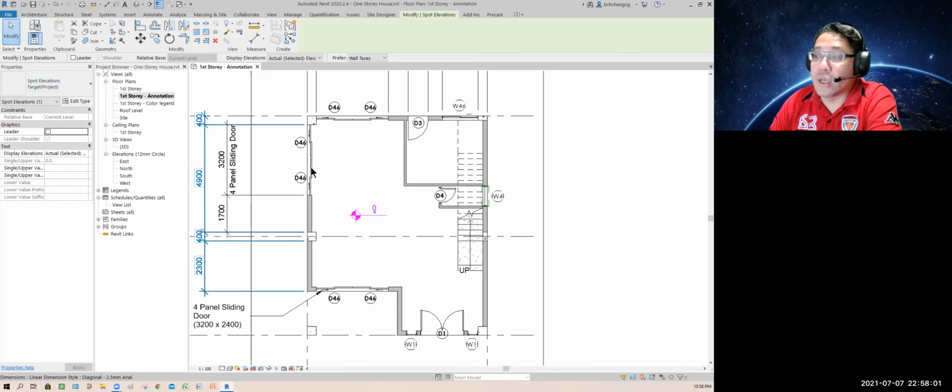If you take it as its own measurement, the project level is correct, because it is still 0. But if you want to tie down to your surveyor or actual site, of course that is your survey point. Project base is for conceptual use, but if you're doing an architectural consultant model, it must be survey level.